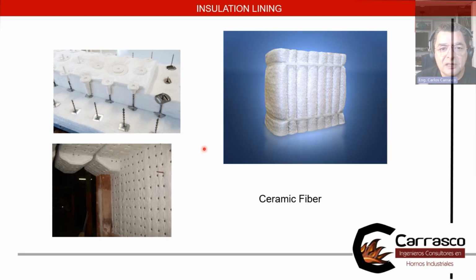The inertia heat of the furnace. You want it to cool down during the loading process, or you want to keep that heat inside the furnace so you don't lose production time between loads. So there are options, and again, you have to consider what my process needs, and then I have to think about it.